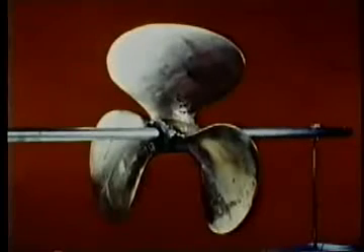Here is cavitation damage on the runner of a large hydraulic turbine, which operated under cavitating conditions for an extended period of time. This propeller operated under cavitating conditions for only a few days. Similar damage can be produced on pump parts, such as this impeller of a pump for high-temperature liquid sodium, and in the low-pressure regions of hydraulic structures, such as this large power dam spillway tunnel. There has even been speculation that brain damage can be produced by the collapse of bubbles in the cranial fluid when the skull is accelerated under the action of a sharp blow.